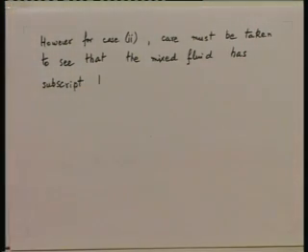The mixed fluid may be the hot fluid or the cold fluid, it does not matter which one, but take care to see that the mixed fluid is given subscript 1 and the unmixed fluid automatically becomes subscript 2. That is the only precaution we have to take. So, these are the two parameters in terms of which the values of f are found out.